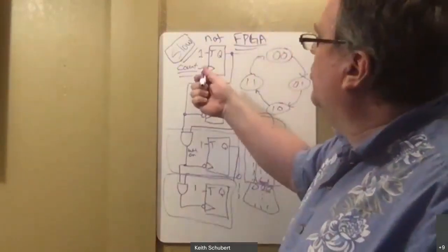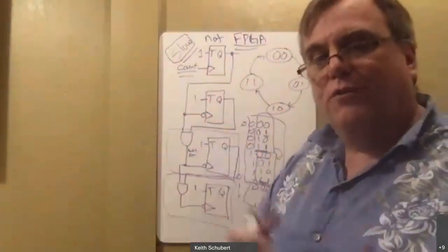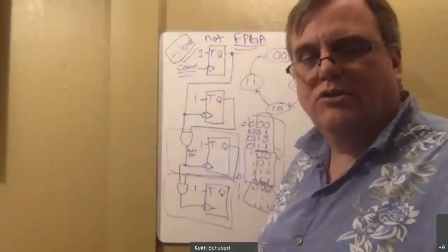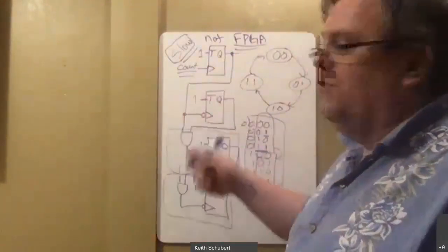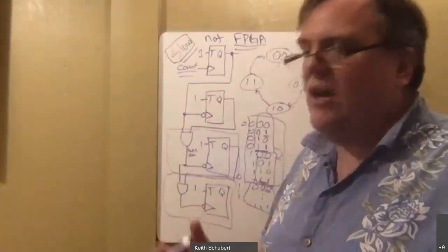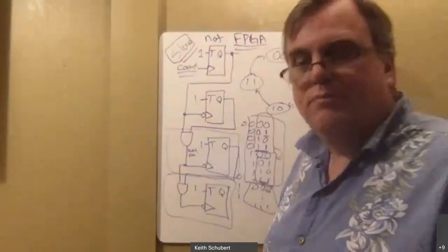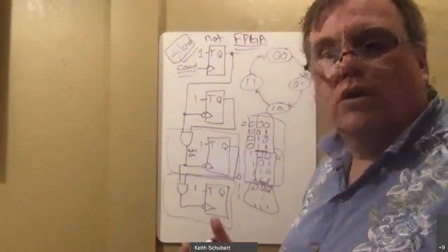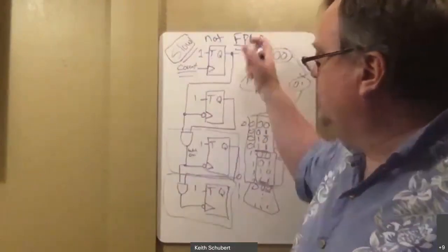And the reason is we're using logic signals into clocks. We've already mentioned that on the first part. Logic signals can't go to clocks on FPGAs, on the standard design setups that we have now. Therefore, it will make a completely kludged together version of this, which will have bad timing and lots of errors, which is what you encountered inside the lab. So you've seen a good example of why it doesn't work. So do not ever do these ripple type counters on FPGAs.